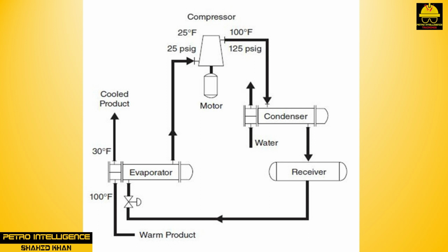In the case of an ethylene refrigeration system, owing to ethylene's volatility, propylene refrigerant rather than cooling water is used to condense the compressed ethylene vapors. No matter how complicated the refrigeration system, the ultimate ejection of heat is always directly to air or cooling water.